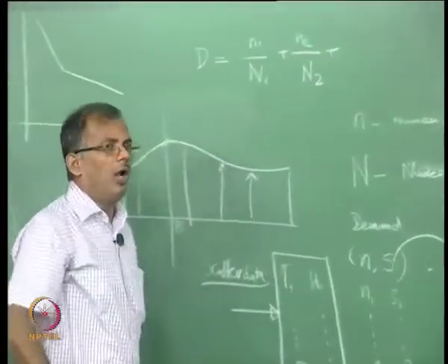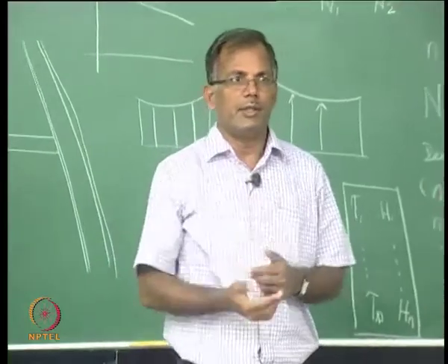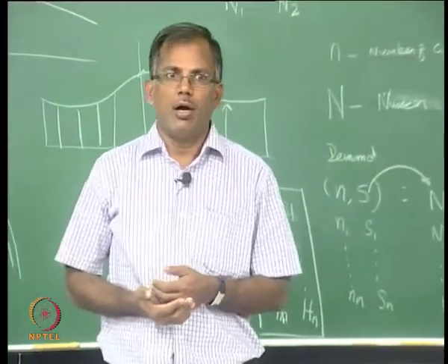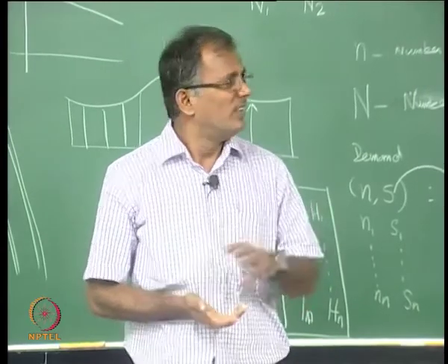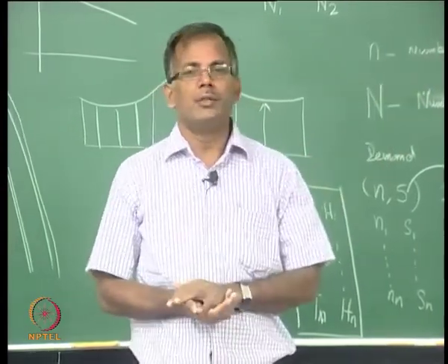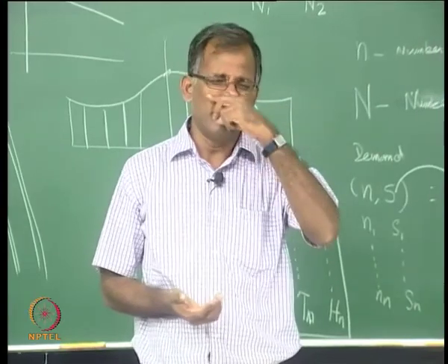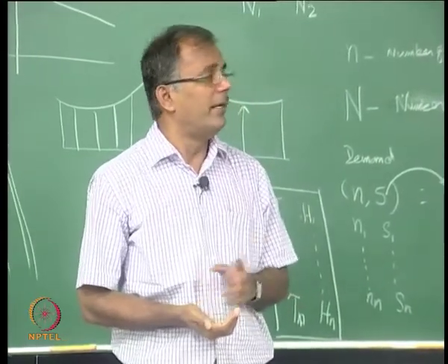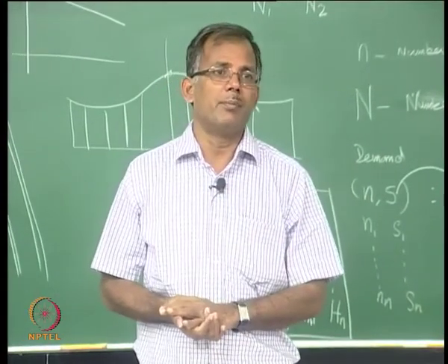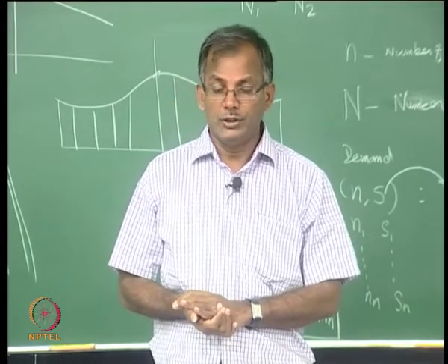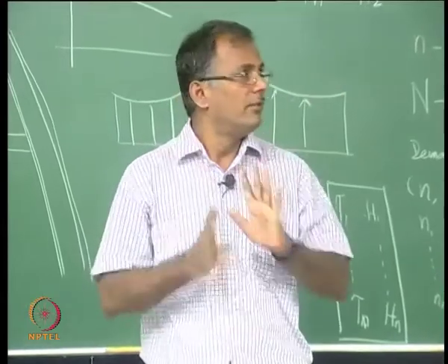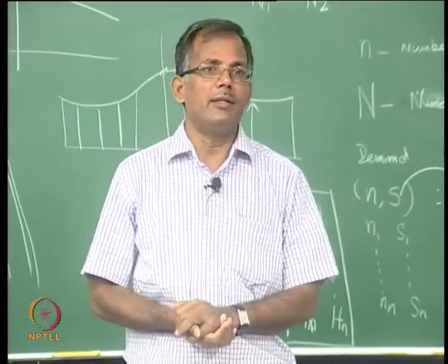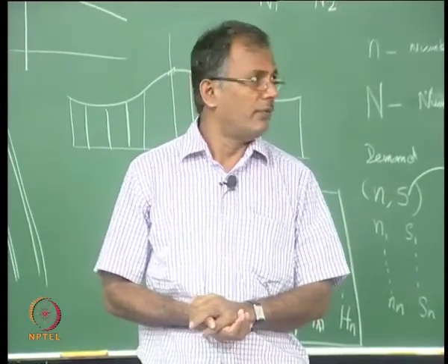until all the data or all the waves in that particular field are added together, which is called Palmgren-Miner's rule, because he proposed this several years back, can't remember the date, but 30-40 years back he proposed this idea, and it seems to be working well, because 100% we use this idea to design the offshore structures for fatigue.